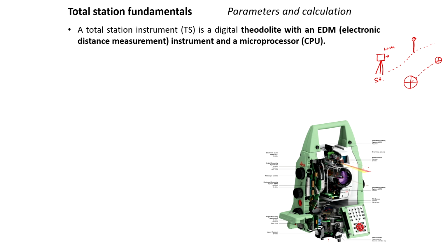Earlier, if you wanted to measure this point, the person would move with the post and move here, and we would take the point and say record. It would record the point, and then again the person would take the post to the second point, and so on. So this required 2 persons: one sitting here, and another one moving with the post. But now with the robotic stations, it can easily sense this. Once you have set this unit, it will sense the prism wherever you are moving, which is what we call locking of the prism. So wherever you move, the station will also move.